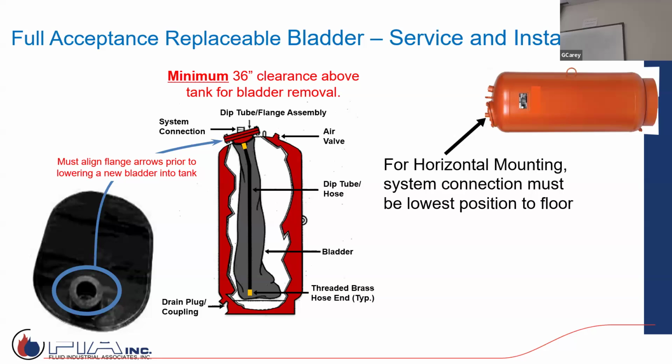ASME, right. Yes, correct. There's a threshold where you can stay below, and as soon as you get to a certain BTU rating, the other thing they might reference is the pressure relief valve on that boiler. If it gets above 30 pounds, so if it's at 40 or 50, now we're looking at ASME commercially. And then you'll find out when they try to cut corners, because from a cost standpoint, getting a non-ASME tank is less expensive than the ASME.